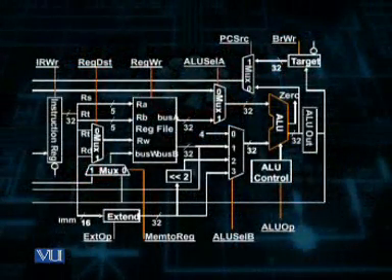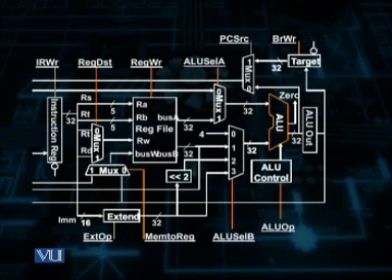Here you can see that I or D is made equal to 1 to pass the ALU out register as the address, or the read address input, to the memory to read the data at the data out.